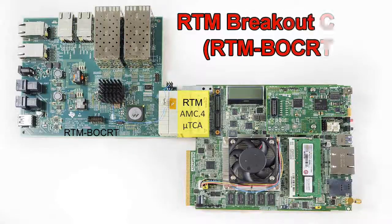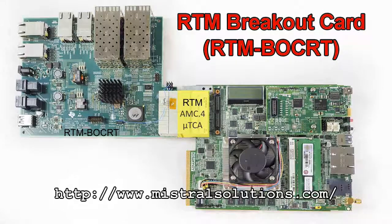The EVMK2H comes equipped with an 8-layer rear transition module to accommodate an optional breakout card from Mistral. The breakout card provides a high-speed digital data interface to the RTM connector for validating 10 gig E and hyperlink applications. The 4 gigabit Ethernet ports have PHY to support the SGMII lanes on future EVMs through the RTM connector.